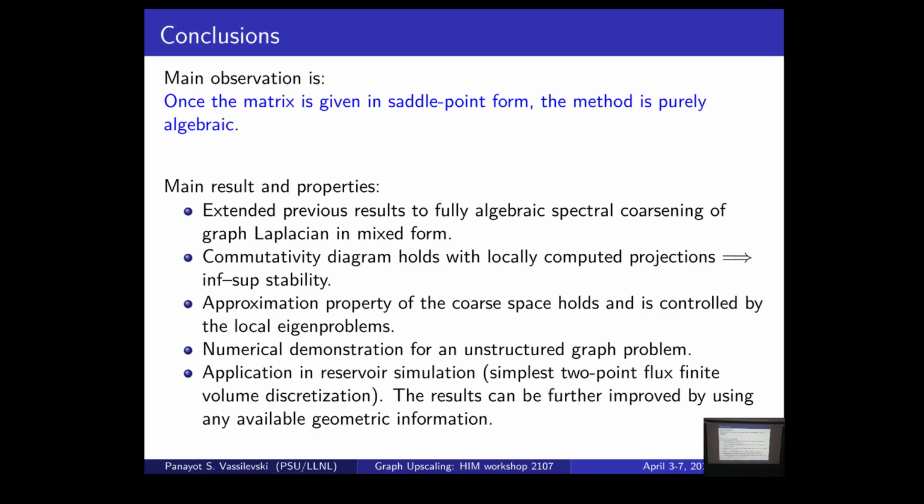And also, one may say, okay, you did this very sophisticated method for this simple problem. I mean, a sum of low-rank matrices. What can you do for other problems? Actually, we're working on that. For any finite element problem which you can assemble from local element matrices, you can come up with the equivalent mixed formulation, because for the matrices, you can factor the pieces in between.